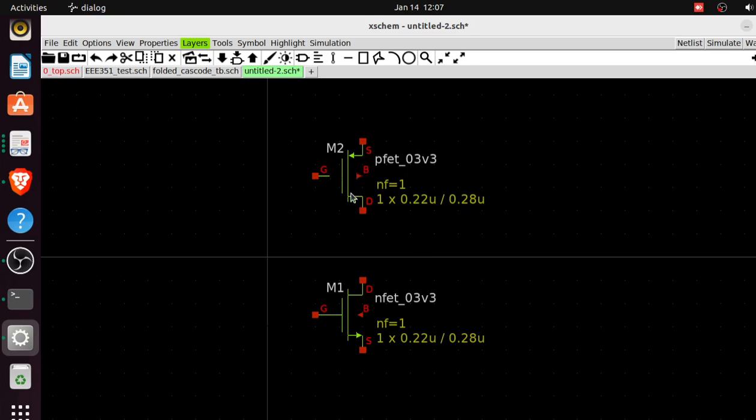Yeah, so I would have my power supply, my VDD up here, then my ground down here, then my output in between. Remember, that's how a CMOS inverter is. Then I would connect the two gates together. So that's what I'm going to do now. For me to do the wiring, you come here to this button, insert wire. So insert wire. Then you just click on the node you want to join, then move to the other node.